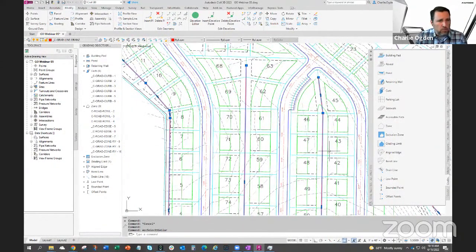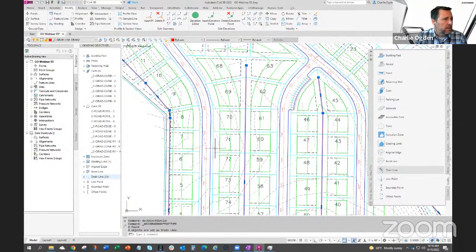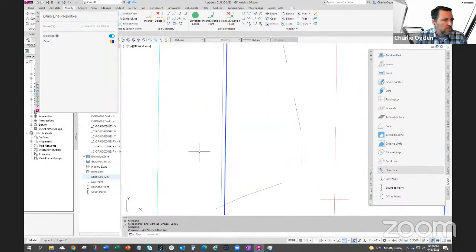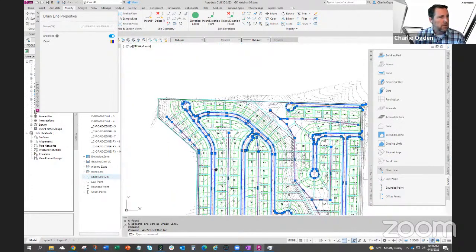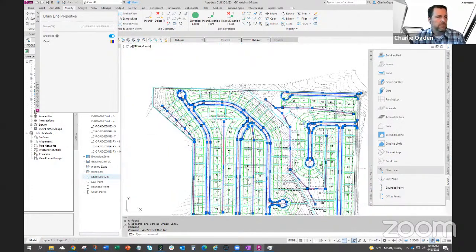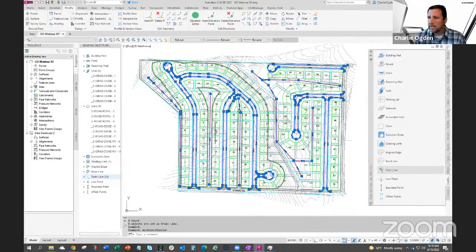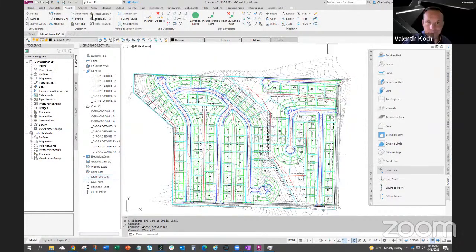So here, let me just add these first drain lines. So what it'll actually do if I select the road ones too, midway between all the drain lines, it's going to choose the closer drain line to go to. So this will end up getting the backs of the lots to go to the back and the fronts to go towards the road. And you could adjust where those are to control where it splits. But yeah, I think we're all set up here. Start grading optimization.